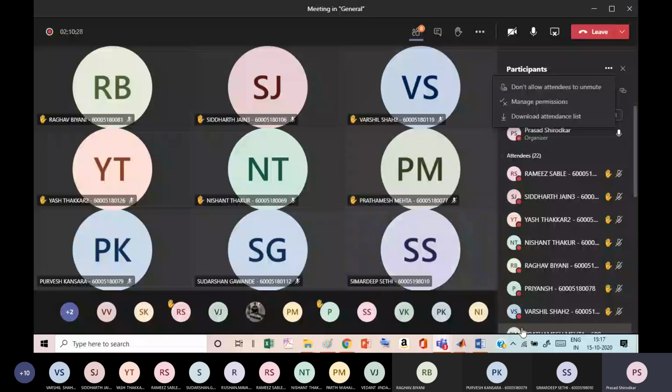And zeta is C by Cc, and Cc is 2m omega n, and omega n is the square root of k by m. So zeta in fact becomes C divided by 2 into square root of k times m. Sir, but in undamped, how will zeta be there? In undamped, there is no zeta, na? Yes, in undamped there will be no zeta.